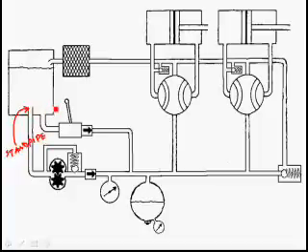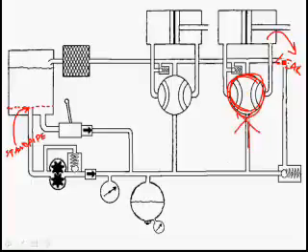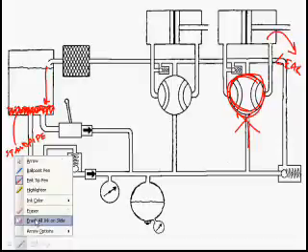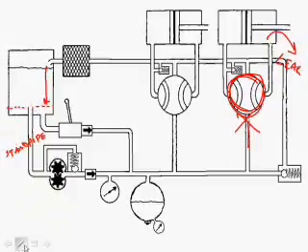You'll notice the standpipe is above the bottom of the reservoir. Let's say we had a really, really bad leak right here. Let's say fluid was leaking out like crazy. If we turned this selector valve to the off position and no more fluid could get out and we stopped the leak, if the fluid level had come all the way down to the top of the standpipe, we wouldn't have any fluid to get sucked in for the engine-driven pump to operate the other actuators.